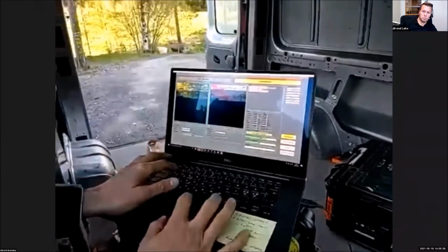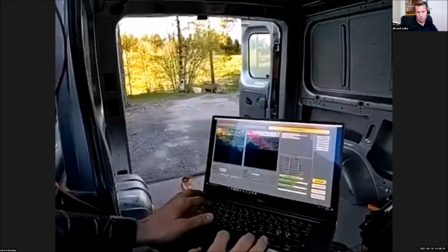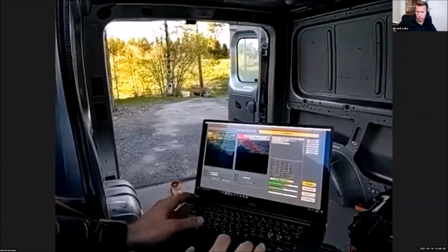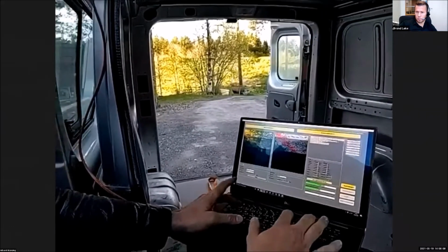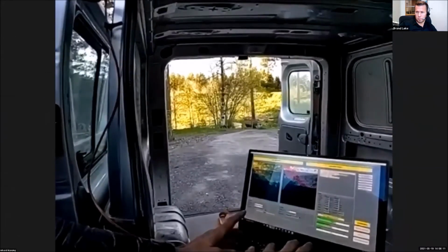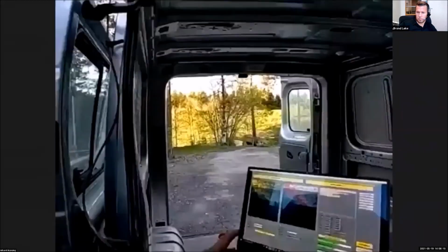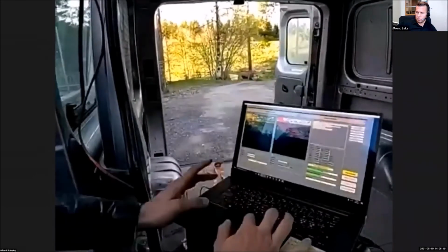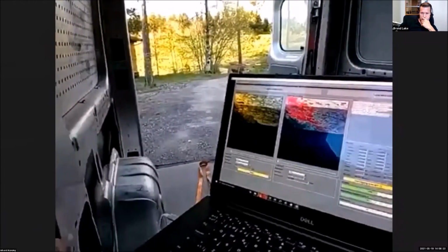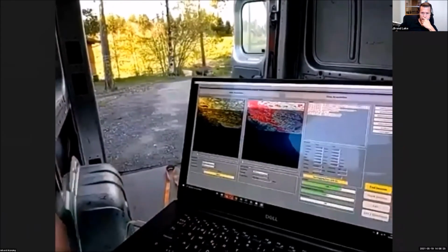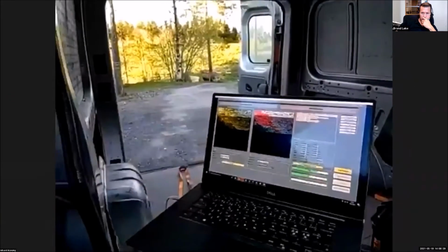So I will turn it down a bit. The shortwave camera has a high gain and low gain mode, so you can adjust the full well. I will adjust down the exposure time to maybe, let's try 15 milliseconds. Now there's a mechanical shutter inside. Now it's closing, taking a fresh dark current for this exposure time. And when it's green again now, it's ready to start an acquisition.